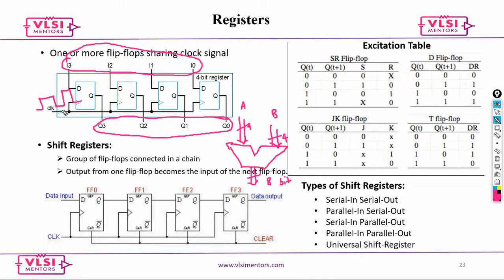So when the computation is out, say after 1 ns, by that time your output should have been available. So you can always put your clock pulse as 1 ns, so that the ALU has enough time to compute and send the signal out.